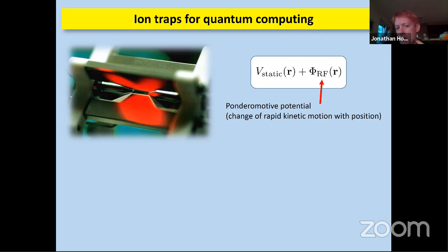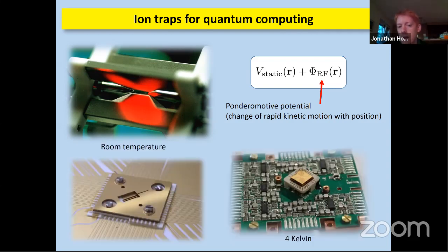But traps in the last few years, as we think about how to scale further, have moved from systems like this one, which is a pile of 100 micron thick wafers, all gold plated and fixed together with now many connections coming in. That is an effort to modularize these systems at some level, all the way to devices which are now made with lithography, because with lithography, we know how to scale complexity very much. And you see that the packaging then starts to become more complex.